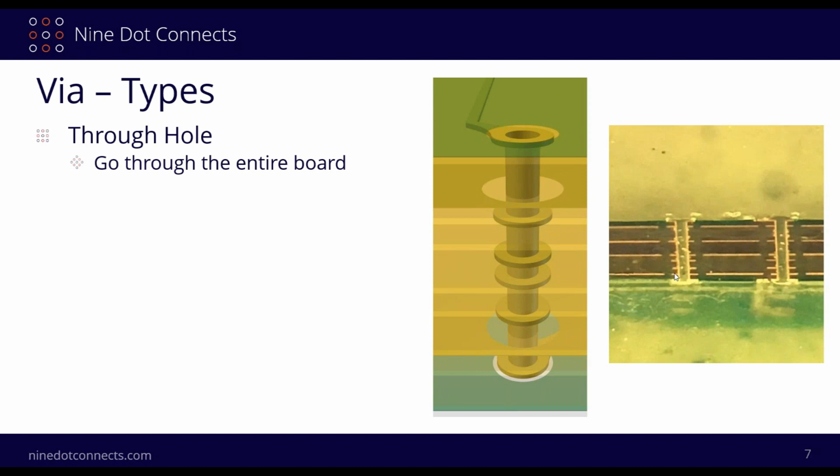They want to make sure that the plating is good. They're also going to want to make sure that the registrations are good as well. So when you get into these things like 18, 20 layers, even at 10 layers, they want to make sure that the registration between these layers looks really good. So they'll make these coupons and then cut them out, and they're just to basically look to make sure that the quality of the fabrication process was indeed there. It's a kind of verification for them. But anyways, what I want to do is show you as many of these 3D graphics as possible to give you a full flavor of it.